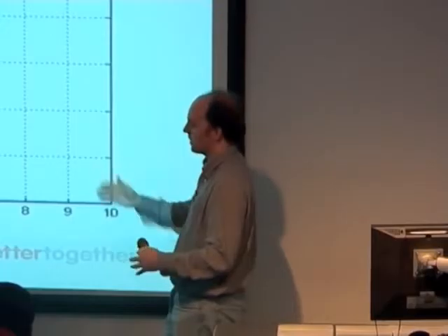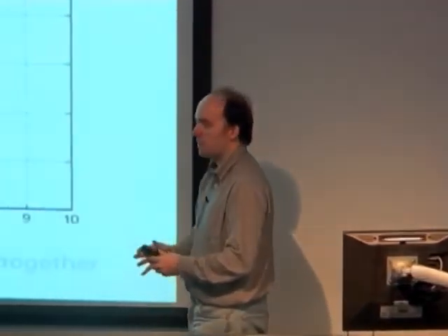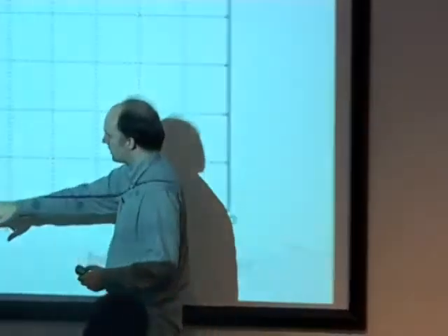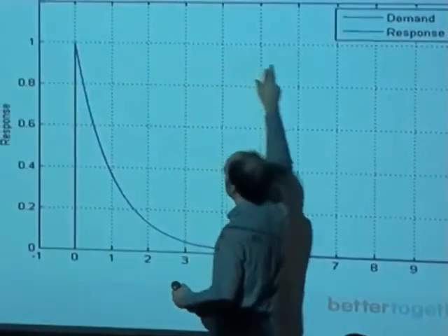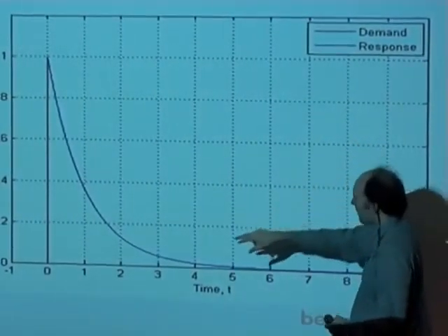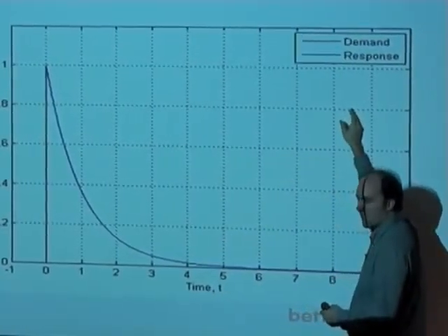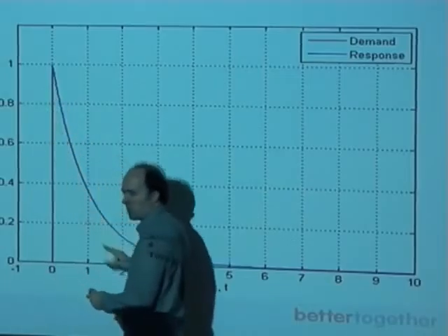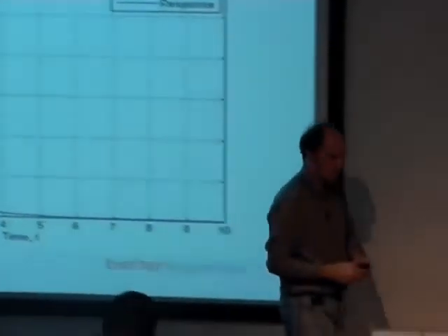So that's what we've done. We've looked at the response for a step input. We've looked at the response for the ramp input. And we've looked at the response for an impulse. And they will always follow these forms, okay? A step will always be something that goes up exponentially to your final value. A ramp will always lag the input, as it ramps up. And an impulse will always start at this value and then drop down to 0.